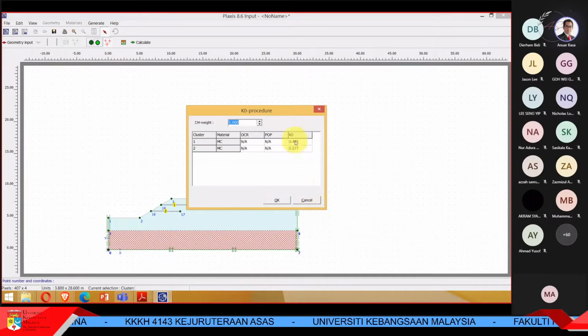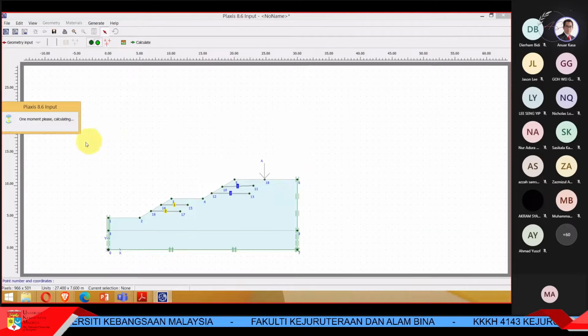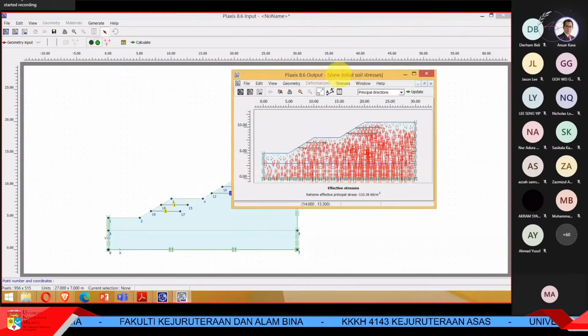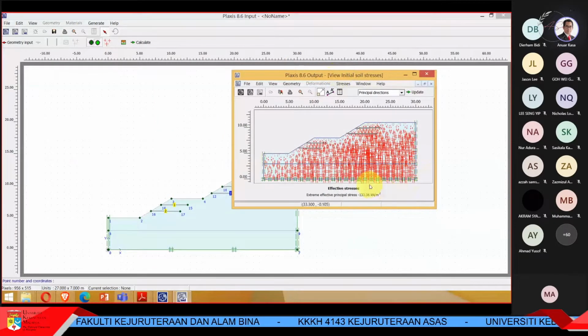Okay. So this is the K naught. If you remember lateral earth pressure, it is calculating the K naught. K naught normally is 1 minus sine of something, something like that. Okay. So it is calculating the stress now. So we get this one. This is the stress, where the highest stress is somewhere around this one, about 133 kilonewton per meter square.